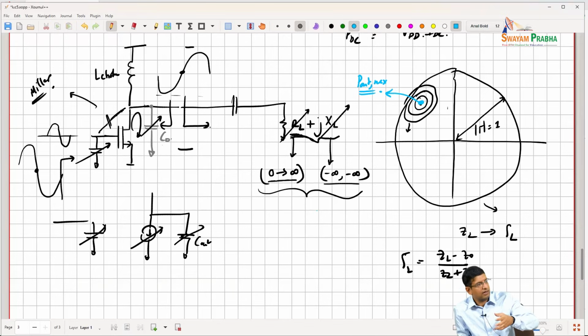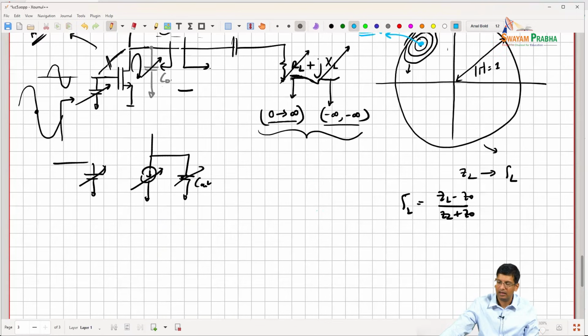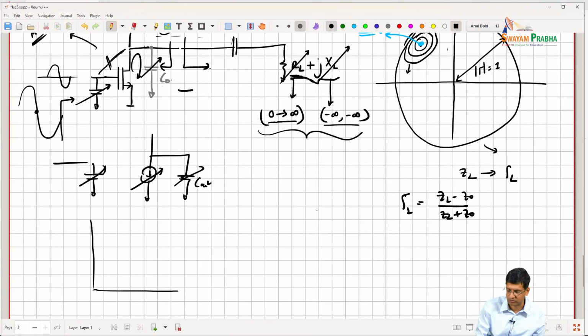OP1dB, right? So I am assuming that there is familiarity with the OP1dB metric, but just to quickly review that: as I am applying a small voltage input or small Pin, I expect my Pout to increase linearly because my gain is linear. But what will happen is that my Pout will start getting compressed, because of the nonlinearities.